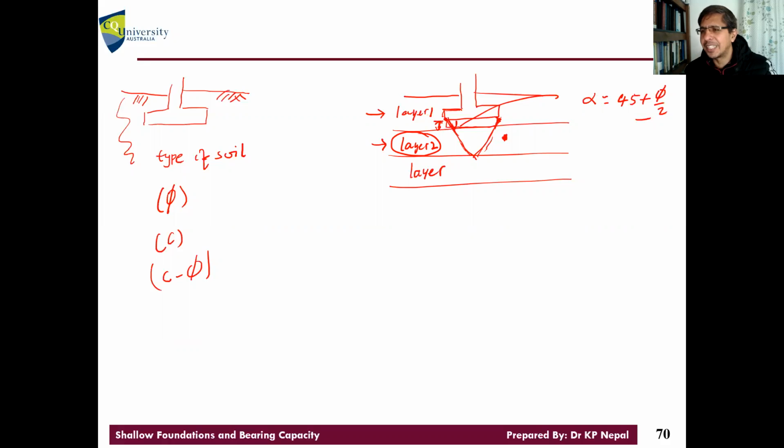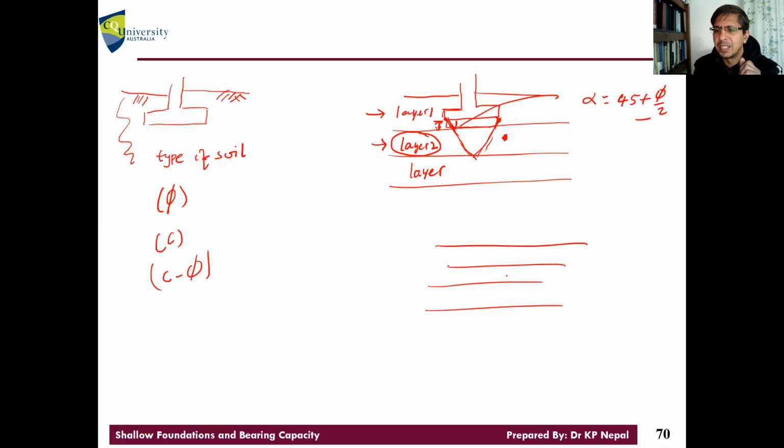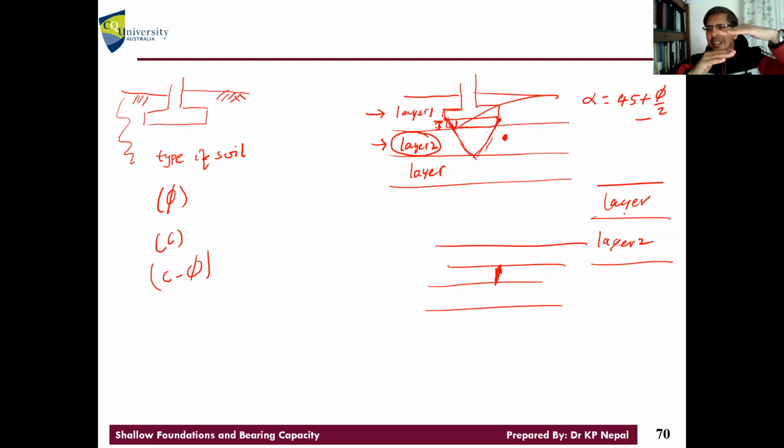But let's learn a few cases where this can be the situation. I don't think that we will have many layers. Forget it. If there are many layers, we don't consider each as a layer, right? A maximum of around 2 layers is enough for foundation design, right? Layer 2 and layer 1. You don't distinguish too many layers and complicate things, right? If they are very thin layers, just scavenge them and put the footing there. If they are very thick layers, then a maximum of around 2 layers is enough for foundation design, right? Layer 2 and layer 1.